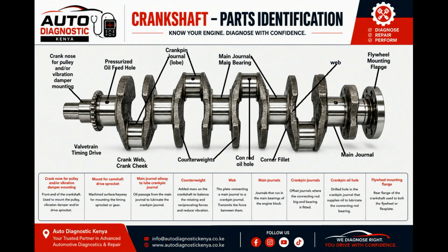But how do those pulleys stay correctly positioned? One common method is a Woodruff key. There is a slot in the crankshaft nose. There's another slot in the pulley or sprocket. The key fits between them. It locates the components and transfers the drive from the crankshaft. Then a nut or a screw secures the pulley or sprocket to the end of the crankshaft. So the Woodruff key isn't simply there to stop something from falling off. It ensures the components rotate correctly with the crankshaft.